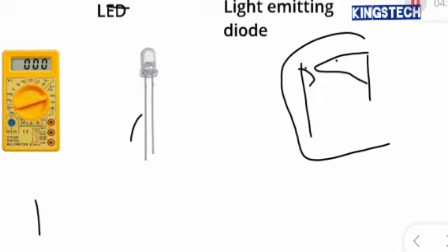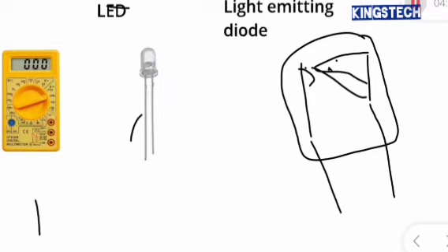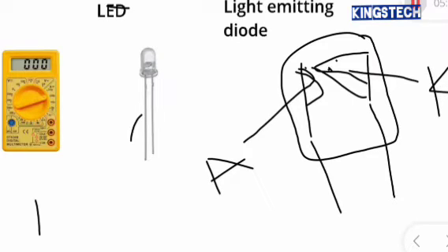Then this is the housing. So these are two diodes outside. You find that inside every diode there is always a bigger plate and a smaller plate. If you look at it, the bigger one is the cathode, while the smaller plate is the anode. Which means this one is the negative and this one is the positive. That is how you identify the negative and positive, by merely looking at the plate size of the diode, probably if the legs have been tampered with.